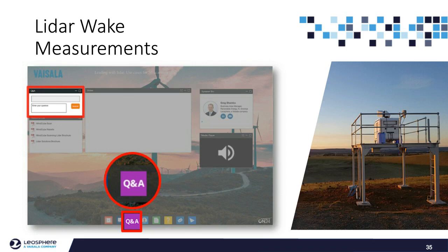Yeah, that's actually one of the applications that is having more interest since there's an increasing size of the wind farms, and there are more wind farms installed in complex terrain. The fact of doing a full mapping of the area is a big benefit. So we have seen also this interest in understanding better the wind flow in complex terrain, and the scanning LiDAR can be really useful for that. And they can also do the wake analysis in this type of area.